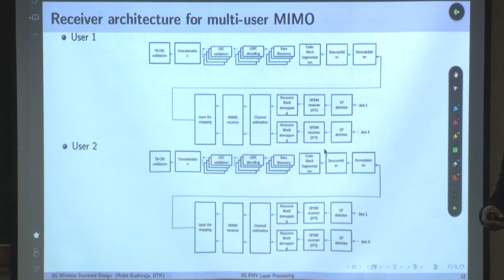And that is how these FR1 MIMO systems are typically implemented, right, okay. Why are they implemented like this? There is a bandwidth constraint of 100 megahertz, okay. Now you want to share this bandwidth across multiple users, and how will you be able to share this bandwidth across multiple users? You need to do completely digital processing, right, okay. And how is that possible? You design this MIMO system with completely digital architecture, wherein you design the precoder separately for each user, you design the precoder for different PRBs, okay. You can do that because there is flexibility of doing it, right. And you are forced to do that because you have to provide higher data rate for all the users, correct, because the bandwidth is limited.